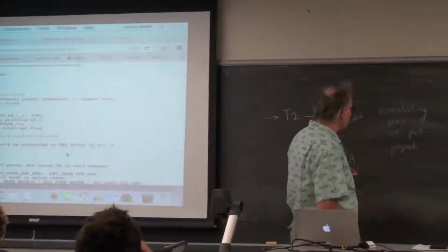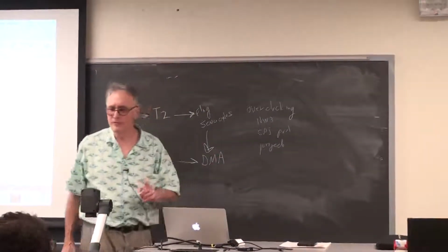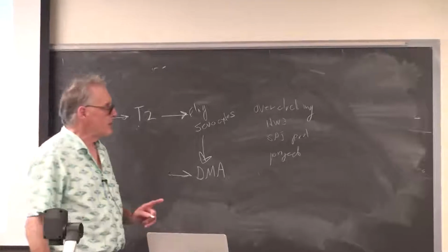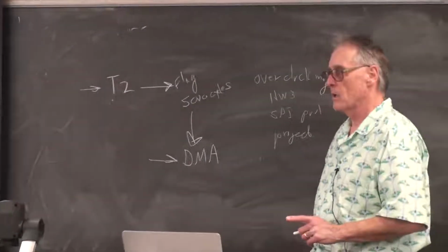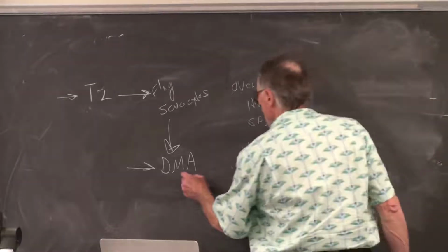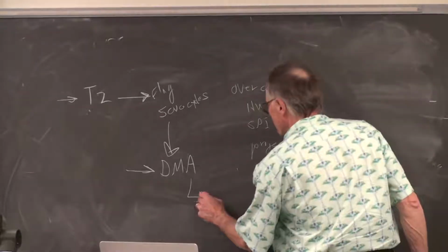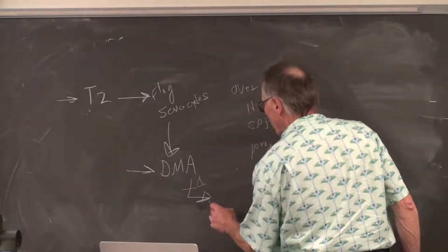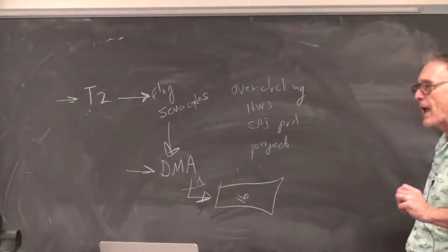That's an interesting question. So, the question is, how does the DMA actually write values? And the answer is that it writes a byte at a time, as far as I can tell. So what happens when it writes 1 byte to a register which is 16 bits long?